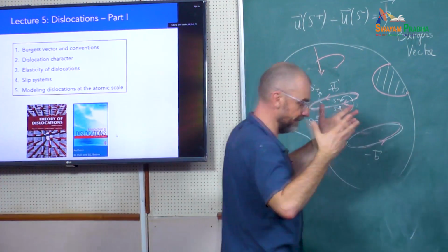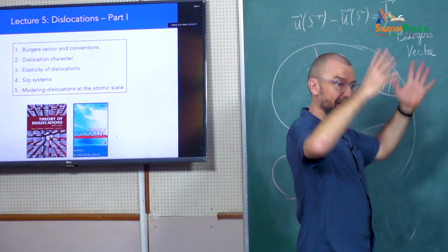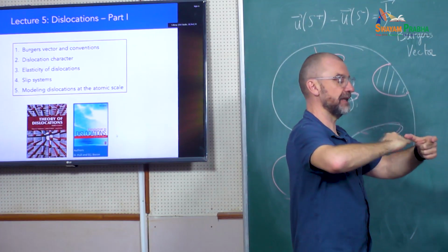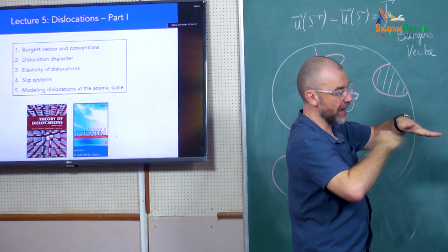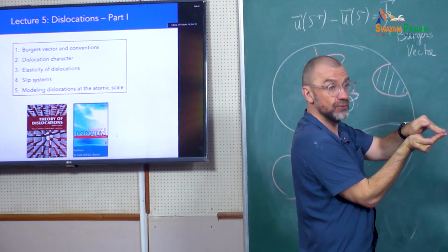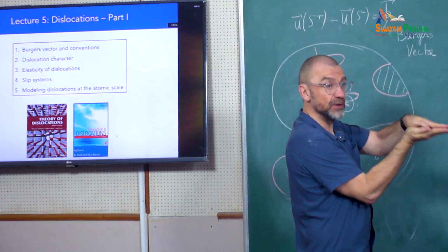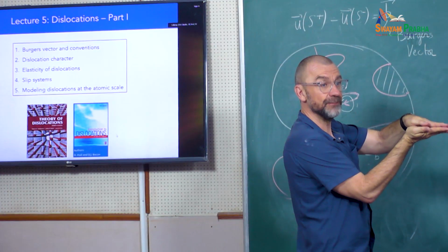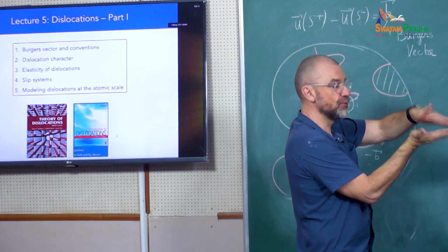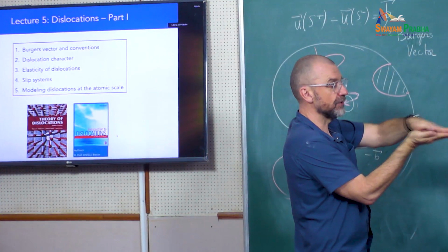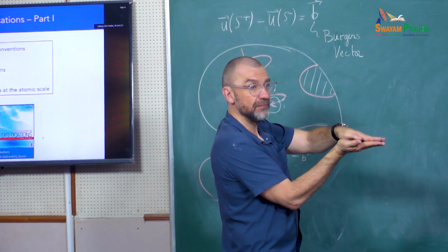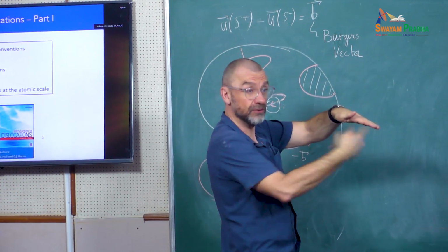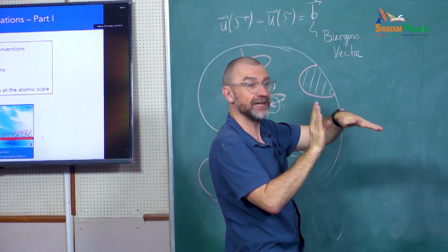So imagine we are in an elastic solid, right? And with my knife, I look at this surface here, I take my knife, and then I make a cut. So here, after I've cut inside my elastic body, I have 2 lips inside the body. It's like I create a small crack inside the body. And then I move the 2 sides of the crack, either like this or like that. If for example I do like this, and I do nothing else, then I've created a real crack. That's not what I want to do. I don't want to create a crack, I want to create a dislocation.